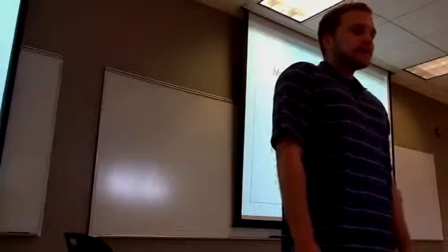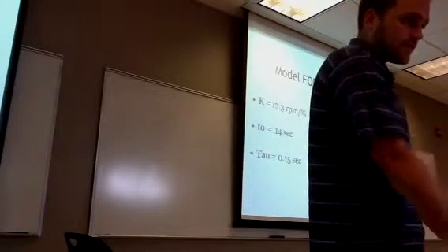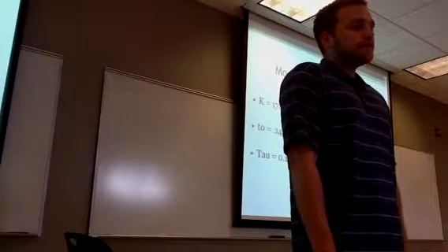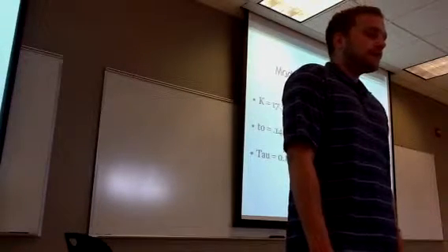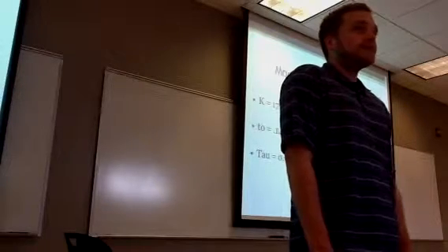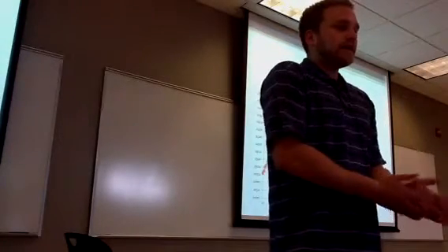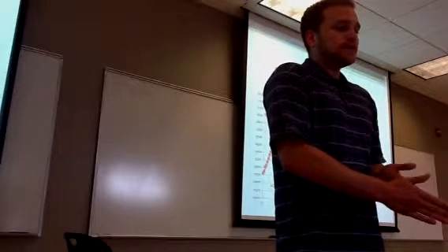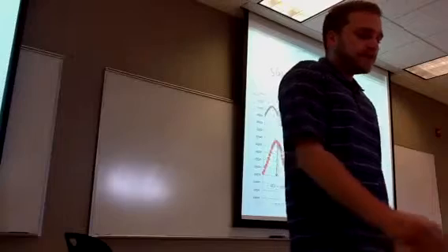Here's the model step down from 30 to 5%. And that gave us the parameters 17.3% RPM per percent for gain, dead time of 0.14 seconds, and a tau value of 0.15 seconds. Here's the sine response with 1 hertz, and it gave us the time between peaks to be 1 second, and the delta M to be 20, and the delta C to be 250 on average.